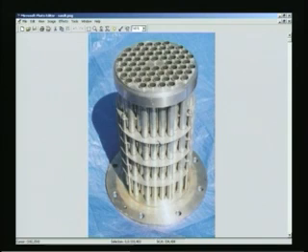You see, this is a baffle plate, this is a baffle plate, to ensure that the shell side fluid flows in a zigzag fashion on the shell side and flows across all the tubes of the heat exchanger. So, I have taken out a tube bundle to show you, so that you get a pictorial photographic view of a typical shell and tube heat exchanger.